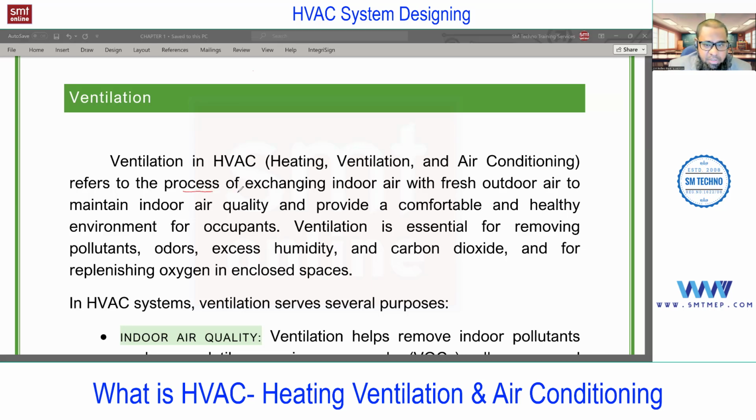So you see, ventilation in HVAC refers to the process of exchanging the indoor air with fresh air from outside. So what do you think? Which is more polluted, the indoor air or the outdoor air? Indoor is more polluted, outdoor is fresher. Here I'm talking with respect to oxygen. With respect to oxygen, indoor air is more polluted, because we are consuming oxygen continuously and releasing CO2.